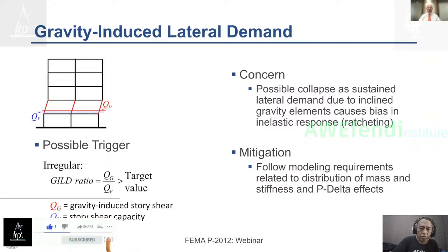I wish that the change had been made in ASCE 7. Some could argue, and perhaps some did at the committee, that since we already have to explicitly think about the strength and stiffness of a system, this should be in any good analysis. I believe that the effect is missed by some, especially if they separate their gravity analysis from their lateral analysis. If they separate those two and they're unaware of this situation, then they may be under designing.